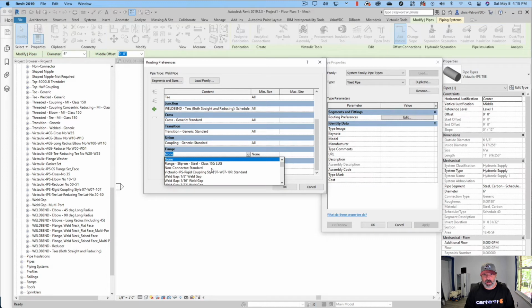And then right here, I'm going to choose my weld gap as a flange. My coupling will be a flanged item. Why? It's just the way that Autodesk has kind of got this set up. I'm really hoping eventually one day that they'll have a space between union and flange that says mechanical joint, so that if you have mechanical joints like a groove joint, a weld gap, a no-hub band, and it's connecting two pieces of pipe together, and you don't need two to go together, then it'll just do that, and it won't malfunction sometimes how this will, where it'll put two in there.